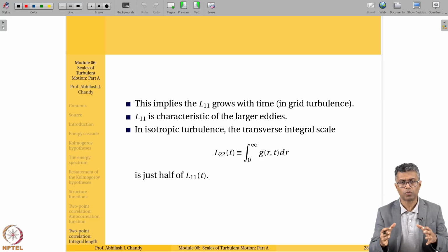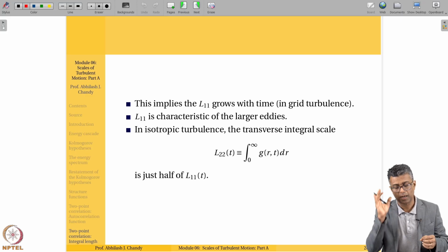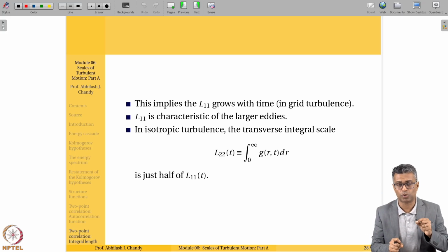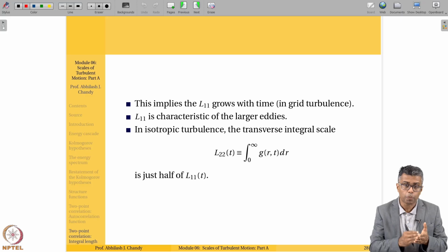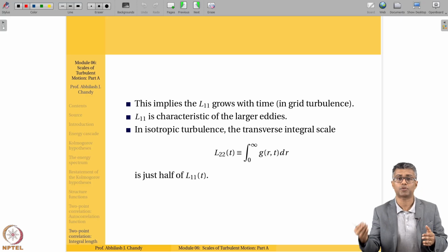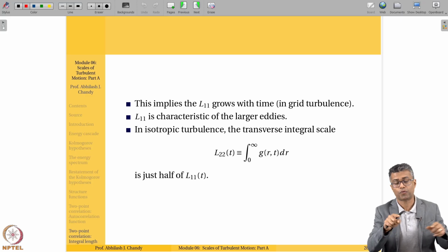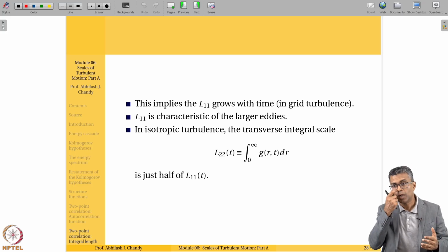We are talking about a problem which is homogeneous turbulence, so nothing is changing with space. That is all okay, but we are also talking about isotropic turbulence, so no variations with respect to reflections and rotations. So that means u1 prime squared is equal to u2 prime squared is equal to u3 prime squared, of course mean of those.